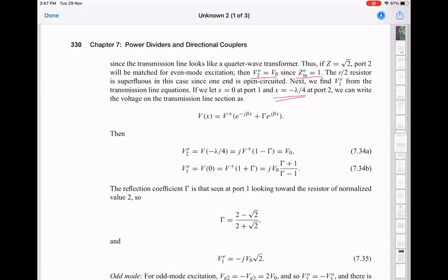And then you have your transmission line equation, which says that you have an incident wave, and then the total voltage at any point is going to be the sum of the incident and the reflected wave. And the reflected wave is just given here as whatever is incident multiplied by a factor gamma, which is the reflection coefficient at that particular port. Right? So we have just taken out an overall coefficient here because there's only one incident wave we are talking about right now.